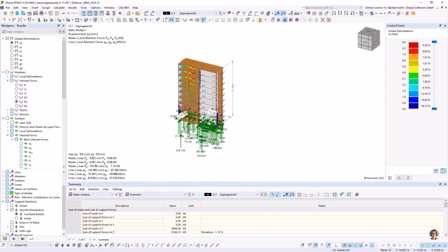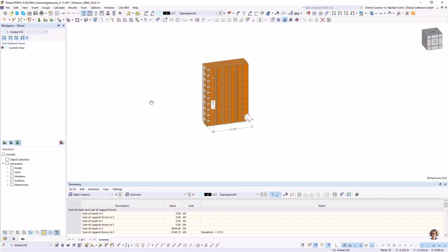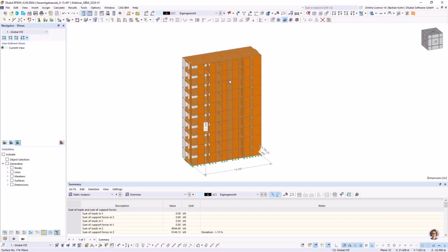But the problem always is when you calculate such a structure in this way, it is not the reality. In reality, such a structure would be assembled from the bottom to the top. And now you are calculating from the top to the bottom, which is, roughly said, wrong. And you should not do it, or you should find a way to regard settling of the structure during the assembly. And what is when a stiffening element is failing or whatever. There are hundreds of things you should regard, and when you just calculate the whole building, it can become extremely wrong.